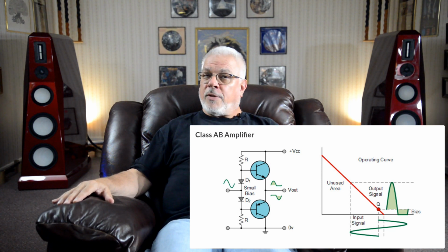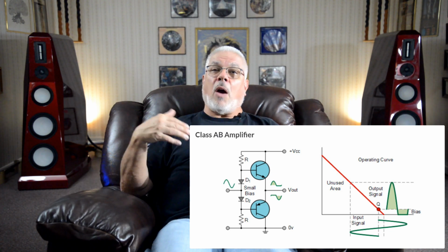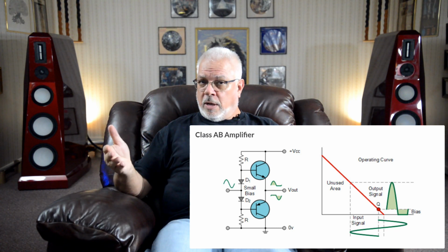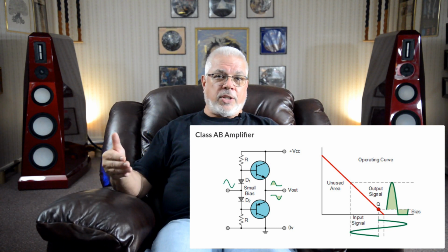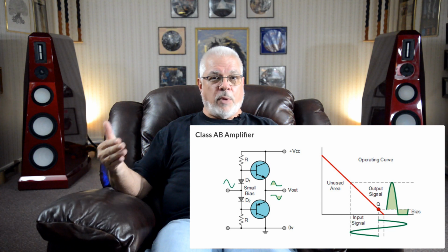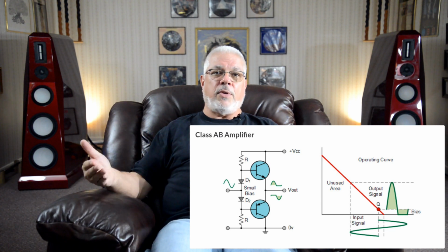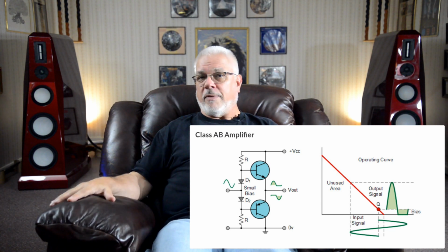This prevents it from ever switching completely off, thereby providing a much more rapid and, to our interests in creating music, more linear response when asked to take over and reproduce its portion of the duty cycle than a pure Class B device.